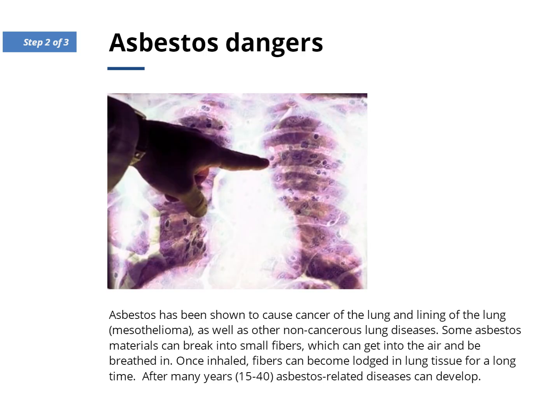Asbestos dangers. Asbestos has been shown to cause cancer of the lung and lining of the lung, mesothelioma, as well as other non-cancerous lung diseases. Some asbestos materials can break into small fibers, which can get into the air and be breathed in. Once inhaled, fibers can become lodged in lung tissue for a long time. After many years, typically 15 to 40, asbestos-related diseases can develop.